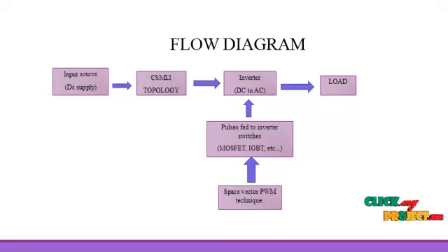The load may be resistive, inductive or capacitive. The topology is developed to overcome the disadvantages of the conventional topology. This is the cascaded topology, with the voltage values and corresponding switching states. This inverter is able to generate all voltage levels, except that it needs an additional DC voltage source and 2 unidirectional switches connected in series with the cascade topology. The developed cascaded inverter is able to generate all the levels. Power switches S1 and S2 and a DC voltage source are used to produce the lowest output level. The amplitude of this DC voltage source is equal to the minimum output level.